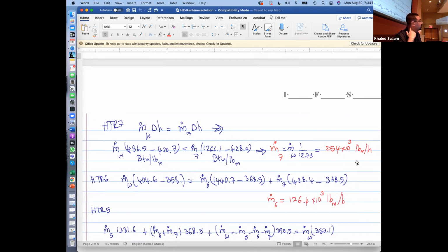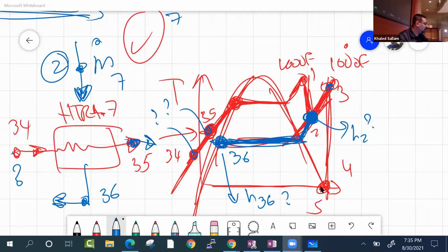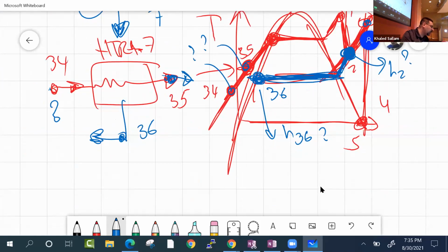I thought it was going to be H out minus H in. So how come it's supposed to be 6? I got a negative. So the question for people online is, if we stick to the sign convention you told us in the first law, and it's out minus in, and as a result, we got our m dot as negative.